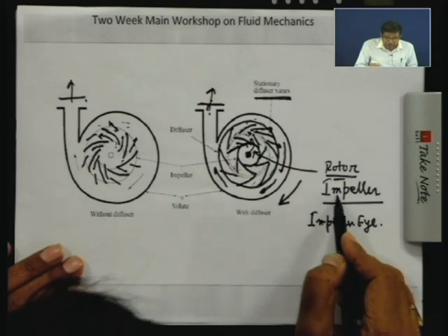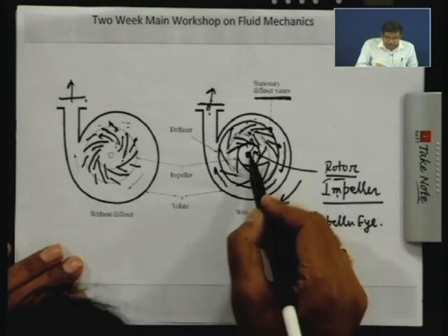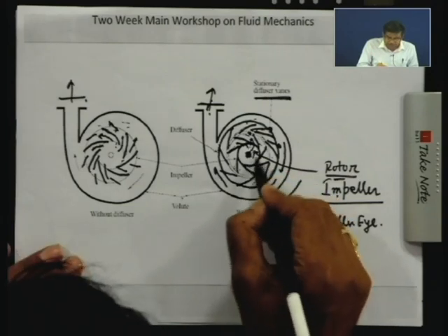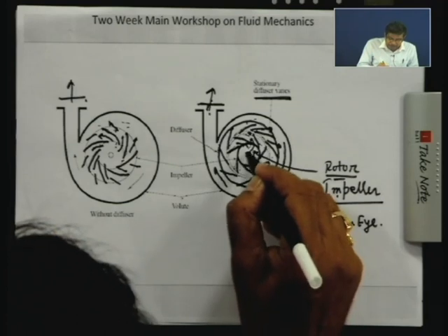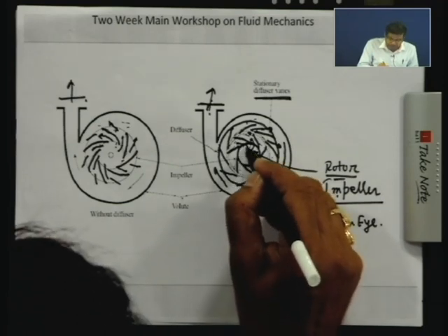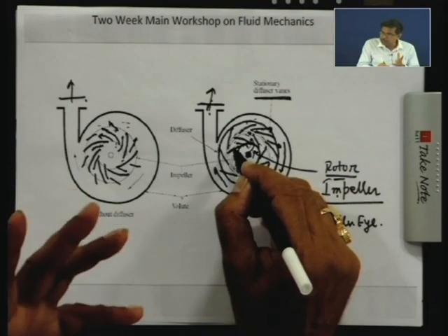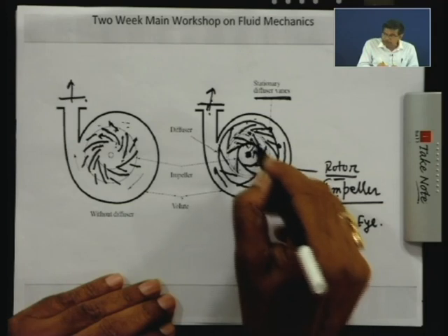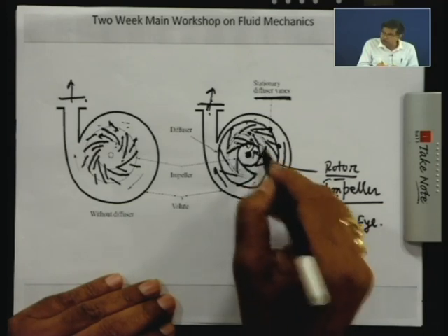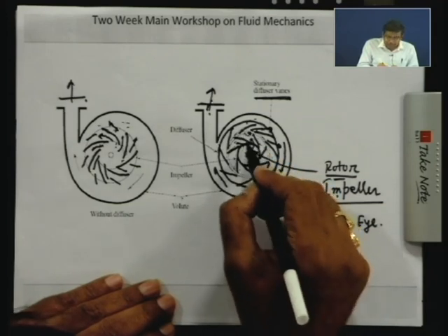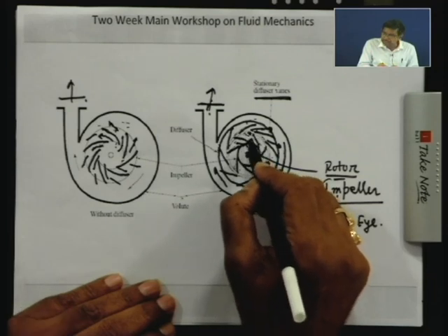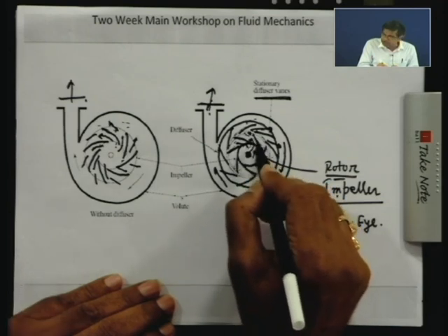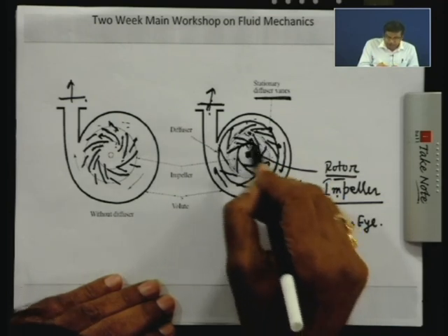Okay. These are the different components of a centrifugal pump and how it works. So, at the impeller the liquid or water is sucked almost in the axial direction. This is the impeller eye where the water is sucked, and it is then immediately turned almost 90 degrees in the radial direction, just the reverse of the Francis reaction turbine. While it flows through the divergent passage of the impeller blades, and the impeller blade rotates, it gains pressure while flowing through the divergent part and gains kinetic energy because of the impulse action, and energy is being received by the liquid or the water while flowing through the impeller.